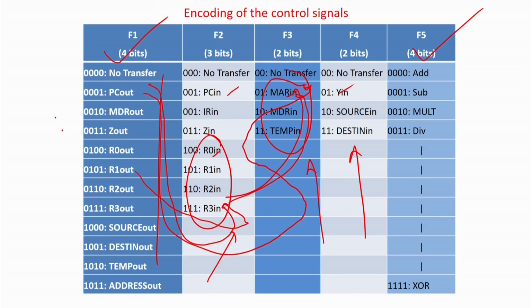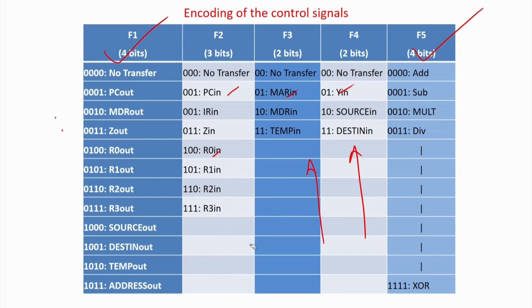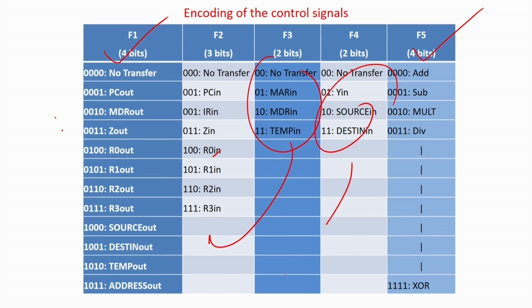If you would have thought that, just like your output, only one register can be input at a time, we could have put all these in another cluster and then you could have saved space. But here they assumed that I am making the cluster based on simultaneous inputs which are possible to the registers. So based on that philosophy, they have divided the signals into different clusters corresponding to that single bus architecture.